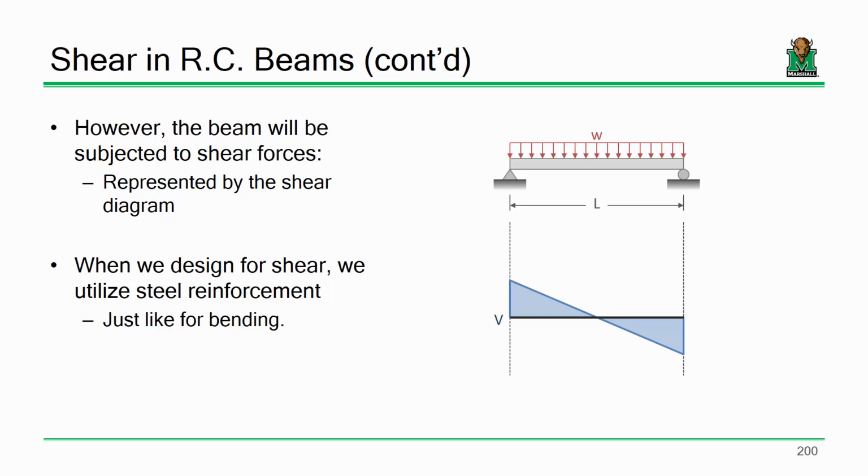Now, one thing that is a little different, and we'll see this later when we get to steel design, it's funny how in steel design I really don't talk about shear very much, because the way that we manufacture rolled I-shapes in the United States, shear really hardly ever matters when you're dealing with a rolled beam. What ends up happening in steel is you'll have like 20 kips of load in shear and like 200 kips in capacity. It's one of those things where shear just doesn't matter. In concrete, however, we have to do a fair amount of design for it.